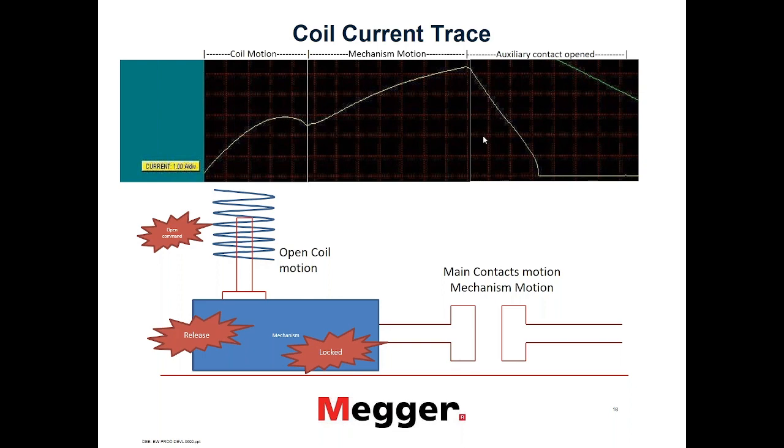So if by online measurement you mean this breaker is in service, you need to connect the measurement clamp to the coil, and once that is set up and done, you'll turn on your test equipment to start measuring and to receive the trigger from the breaker tripping or closing by the system operators, and then you can get this measurement value.